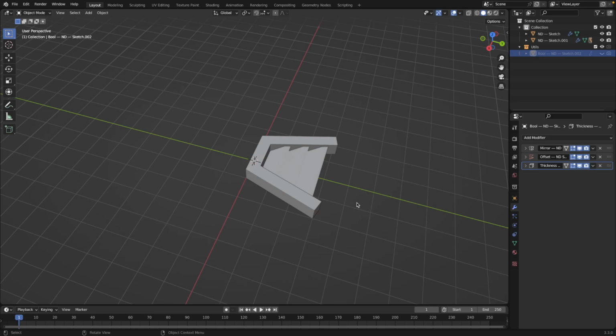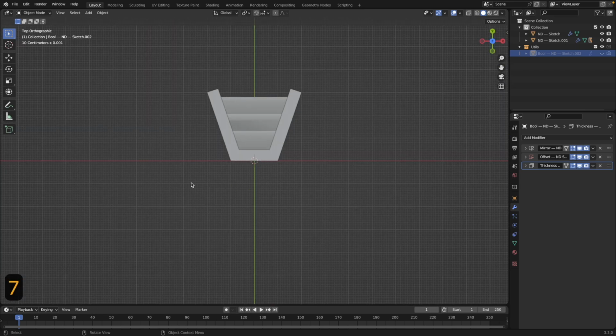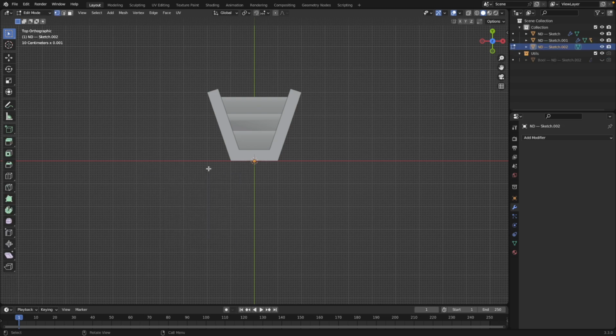There's a couple ways I could do that. Probably the easiest way for now will be just, let's go into this mode and let's create a new sketch again. So there's our single vertex. We're gonna move this vertex up this way. We're gonna put it like maybe here. We'll extrude it along the x-axis straight this way, like that. So this is the line where we want to cut that thing.